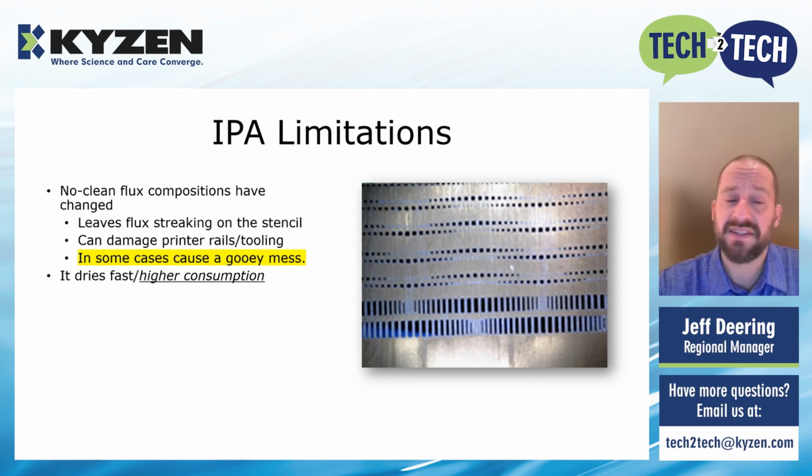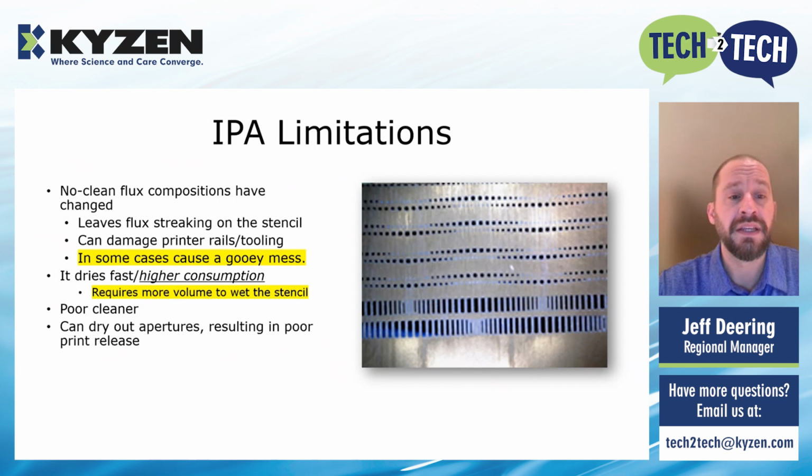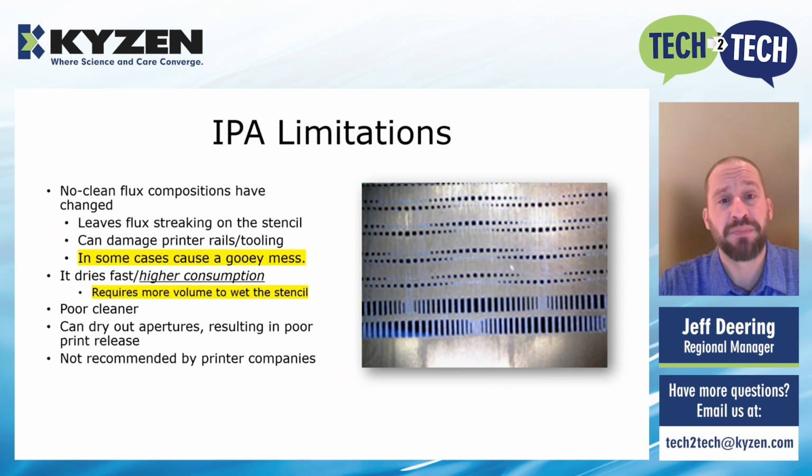IPA dries fast, again, having a higher consumption rate. It requires more volume to wet the stencil, like I had mentioned before. It can be a poor cleaner. It dries out apertures, which results in poor print release. It's not recommended by printer companies. And most importantly, it's flammable.